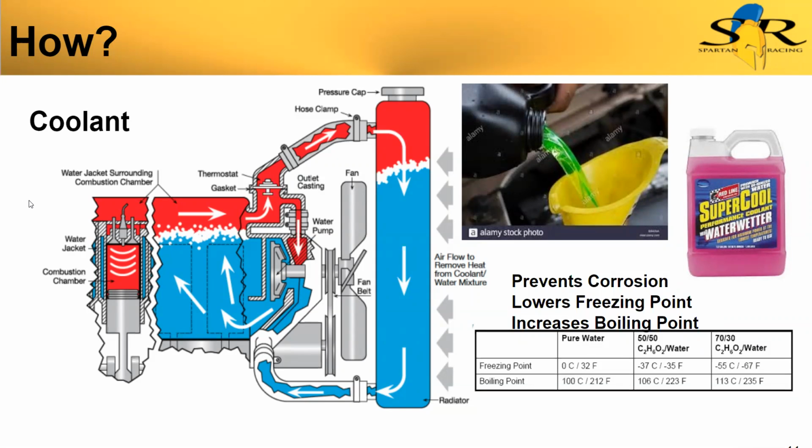That's a great point. Absolutely. Especially in cast blocks and engines where the surface is really rough, the water naturally won't want to get down into all those little grooves and valleys. So having something with very low surface tension will really help keep bubbles from forming and help make good contact between the engine block and the coolant.